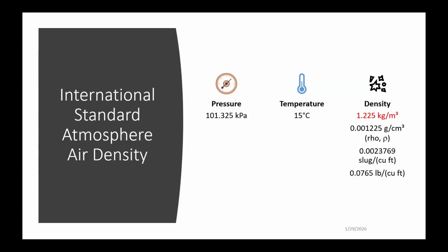The key with this, when you look at the equations for air density, is that when pressure decreases, the density decreases. So as you go up in altitude, the air density decreases. As the temperature increases, the density decreases. Now, the air density is going to determine our performance and our safety limits, but air density is not something that we see directly on any of the instruments we have in the plane. But if you've got an engine, your performance decreases as you go up in altitude.